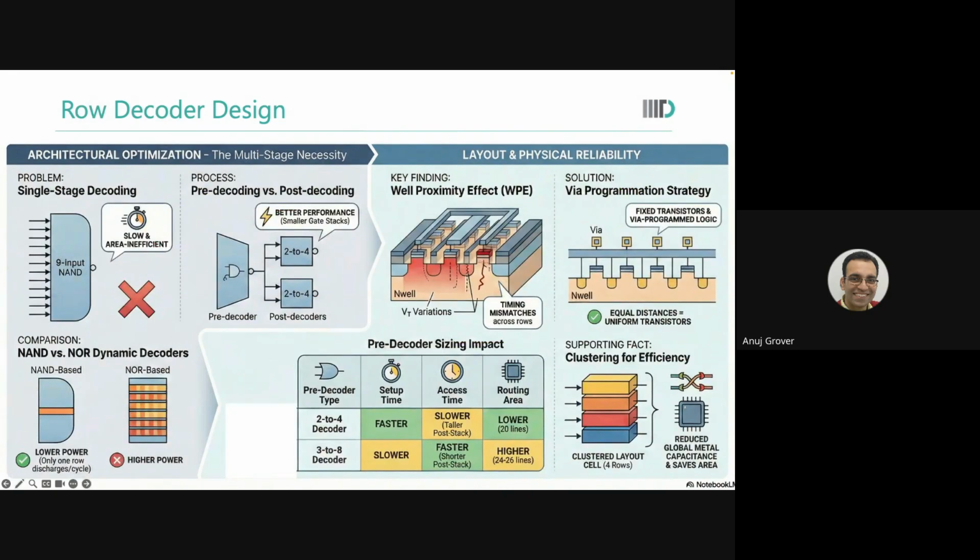Finally, in the row decoder, where it has to select the word line. That is where the clock meets. So all the address decoding has to complete before the clock arrives. All that series of AND gates and NAND gates that we were just looking at have to complete their evaluations before the clock arrives. Setup time increases.